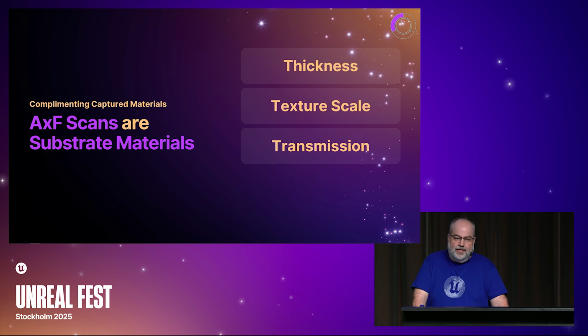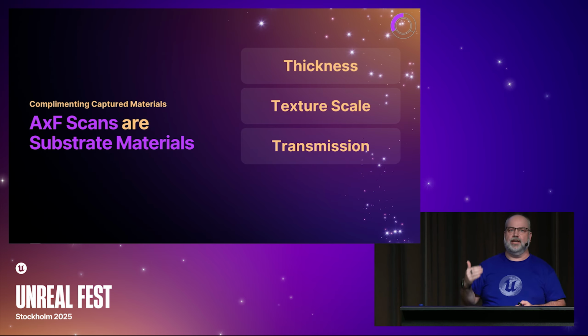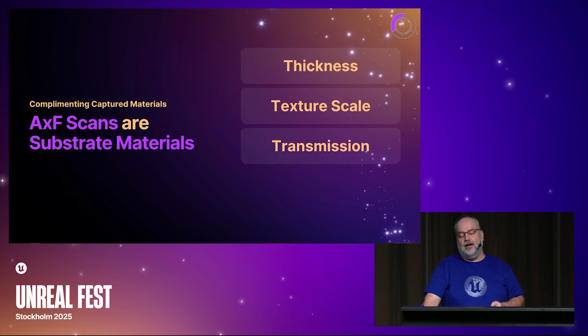And that leads to the transmission of how this stuff works. If you don't use transmission, you won't be able to see it. So a cool example is if I have a base coat that has a gray primer on it and then I put a base coat over it, with Substrate, I can actually scratch it because I can put a thickness map on there and basically scratch it down to that bottom layer. But if you don't scratch it, you don't see it. And if you don't see it, it doesn't get rendered, so it gets optimized out. It's really powerful. And I think there's some really cool stuff to be done there in the manufacturing space.